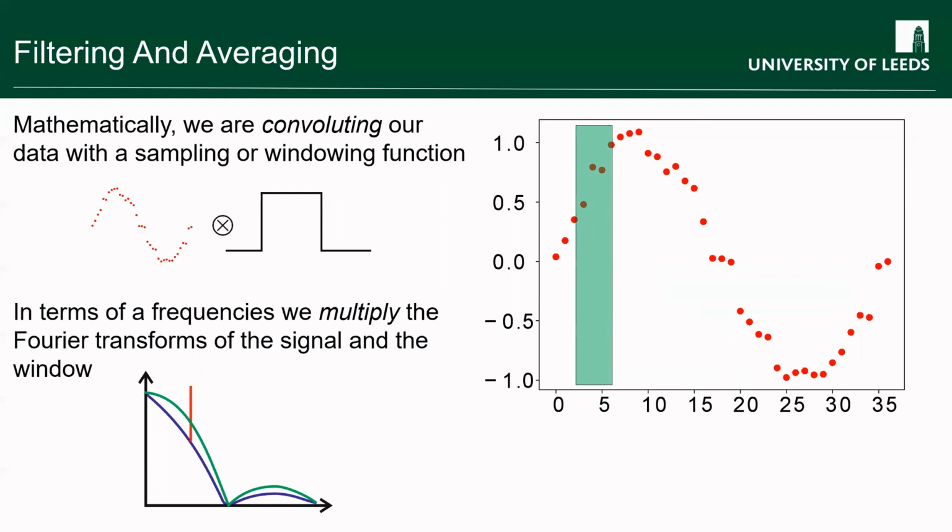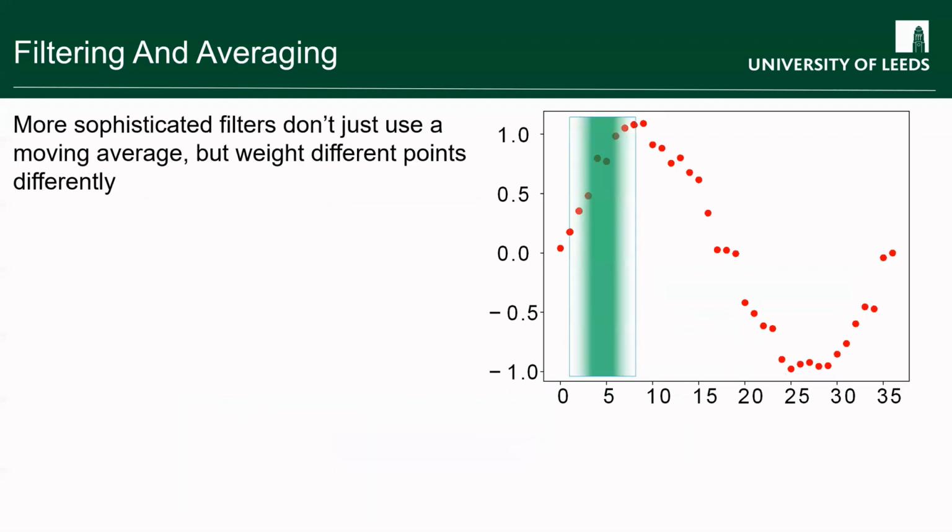So we get rid of the high frequency noise and we keep just the bits of the signal we're interested in. But what's actually going on here is, yes, we've reduced the higher frequencies, but because of the shape of the Fourier transform of the filter, it's actually reintroducing some high frequencies again. And so you get these distortions in the signal, which are coming from the filtering. It's almost an aliasing effect in the filtering: the effect of the filter isn't to just suppress the high frequencies, they come back again.